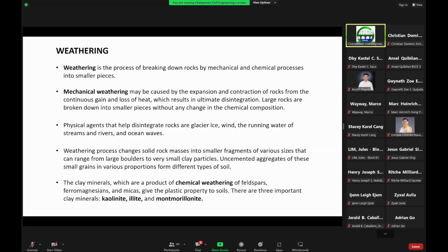So in the borehole log, you can see in this depth boulders, the next cobbles, the next sand, silt, clay, then again boulders, and so on and so forth. And that will be the basis of your geotechnical analysis later on to give the bearing capacities or the pile capacities, for example, that is needed by the structural designer.